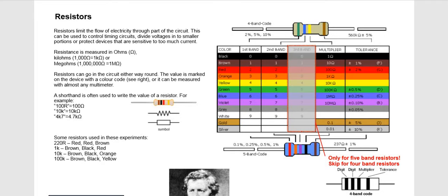This is the first, right up to the last, and following the table here, you can see that every color has its number, its digits, its multiplier value, and its tolerance value. If it's a brown, for instance, the first band is always 1, the next one, and the multiplier is always 10. The tolerance is plus or minus 1%.